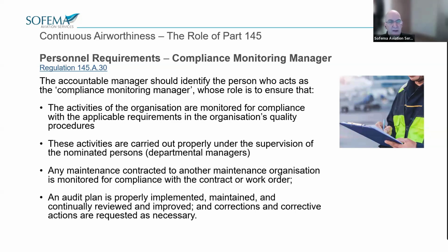So a couple of key points. The compliance monitoring manager should not be one of the persons I've just mentioned that are managing an operational area of the AMO. They should be able to demonstrate relevant knowledge, background, and appropriate experience related to the activities of the Part 145, including knowledge and experience in compliance monitoring. Also, they should have full access to all parts of the organisation in order to inspect it and carry out audits.